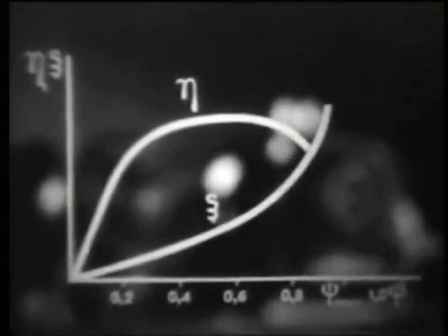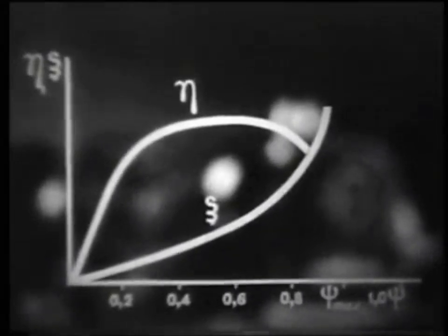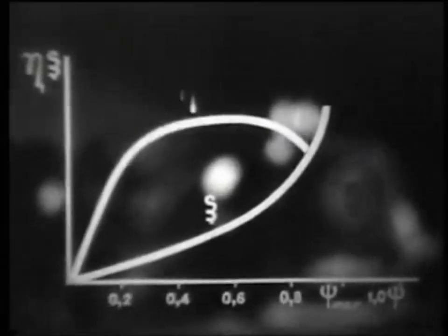The greatest hysteresis losses occur on the pulley when the belt bends on it, as well as losses in bearings and aerodynamic losses, which do not depend on the load. Therefore, the transmission efficiency at low loads is low. As the load increases, the efficiency increases, reaching a maximum in this interval, and then, as the slipping increases, it drops sharply.